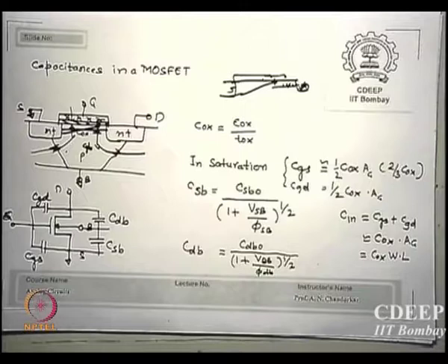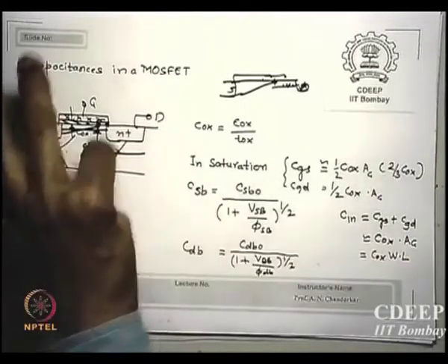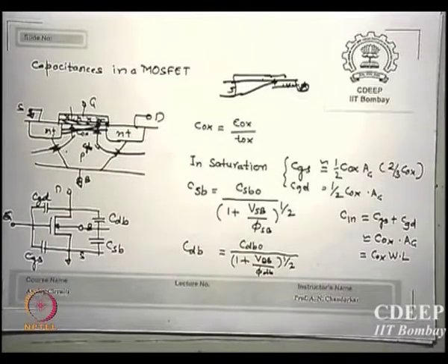Is that okay? The depletion layer will enhance with applied bulk bias. And if that happens, will the capacitance increase or decrease? If I make VSB more negative, what will decrease? The capacitance decreases, because the capacitance goes as epsilon by D, so if D increases, the capacitance falls. If the capacitance is smaller, is it more worrying or is larger more worrying?